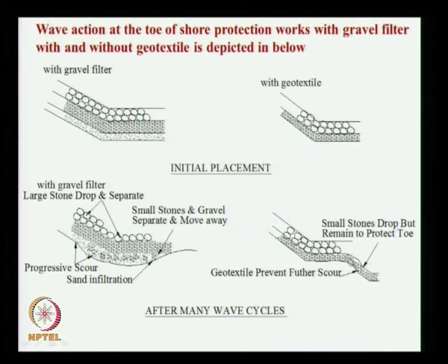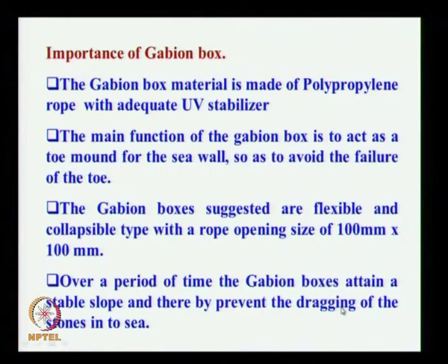The small stones may remain down, but they stay there to protect the toe, but this alone is not sufficient. As you see here, there is a potential failure at the toe, so here we have provided gabion boxes to further strengthen the toe protection.